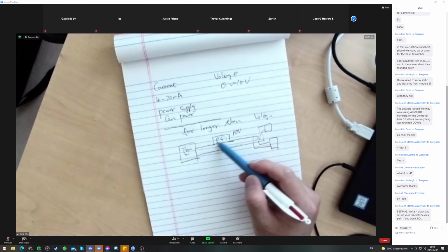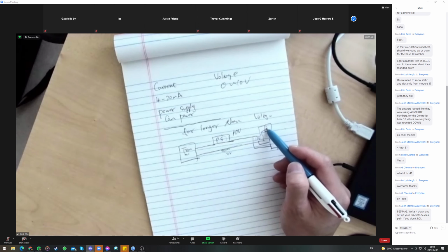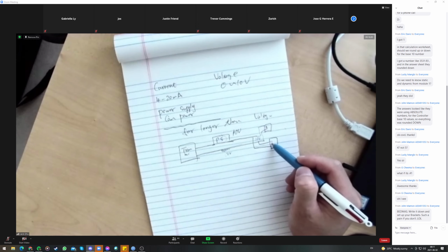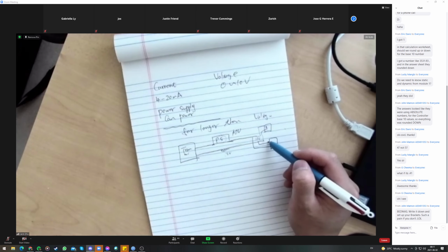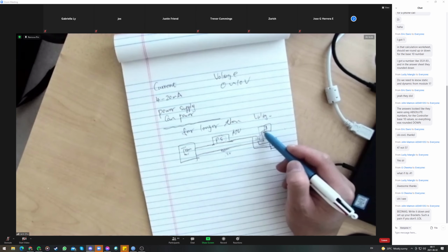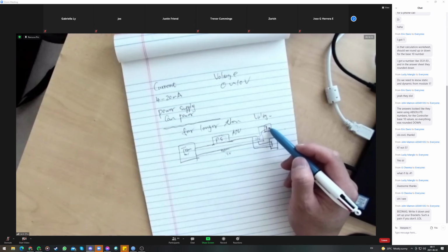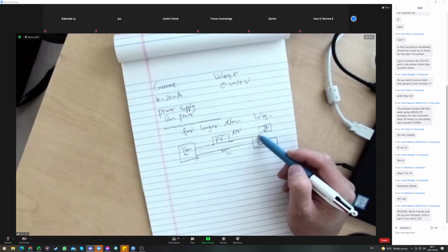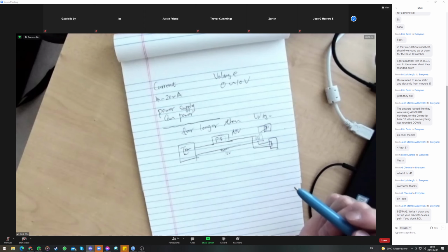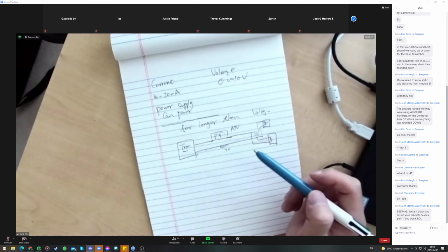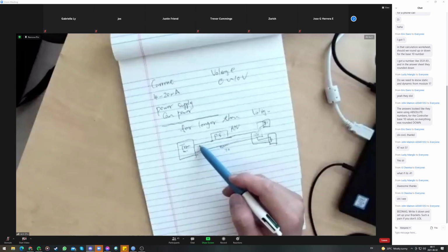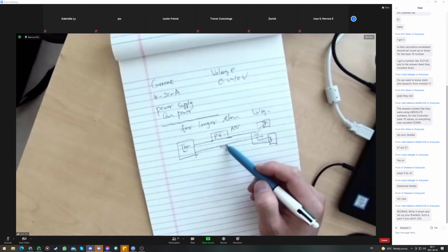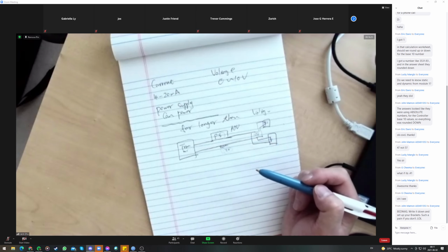And for this one, because each of those equipment has an internal, we call it internal impedance, they will draw a current. When they draw a current, they also will have a voltage drop down there, and then you want to keep the 10 volts here. So it will be slightly harder to plan out how far you can go with the voltage drop on the wire.